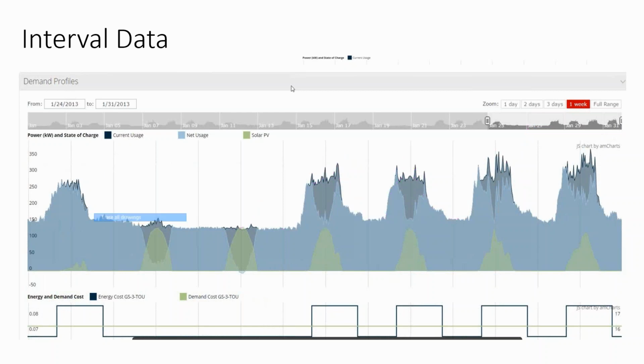But we also see the problem being illustrated with a solar array. If we add this solar production that's shown in green here, it's going to reduce this midday peak, but even though this is peak energy being taken off of the grid, now our shoulder peaks in the morning and in the afternoon become where our bill comes from.